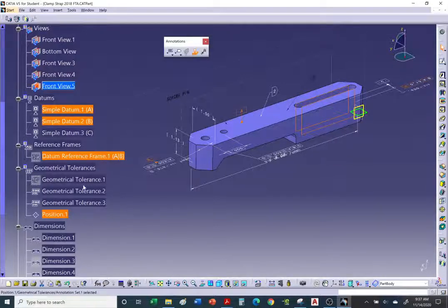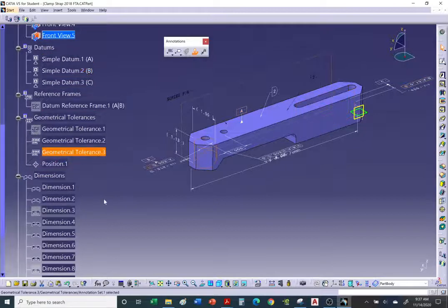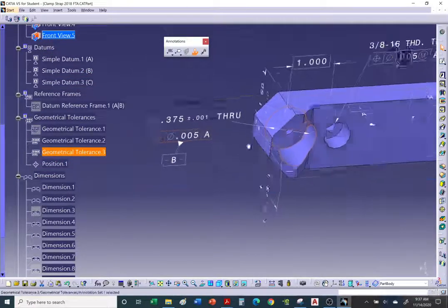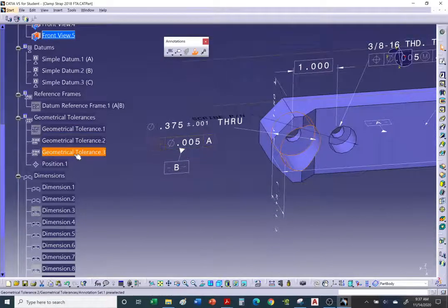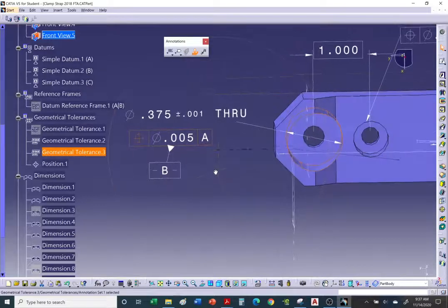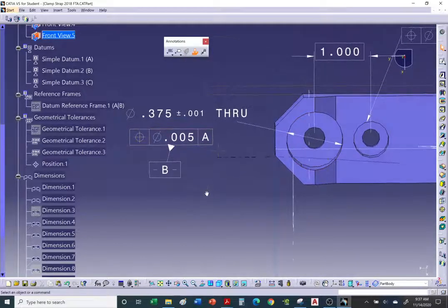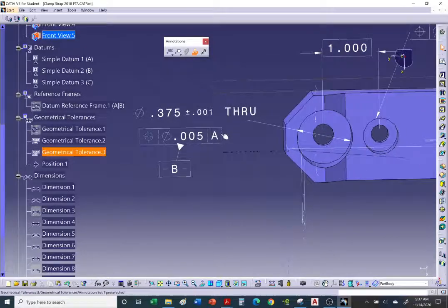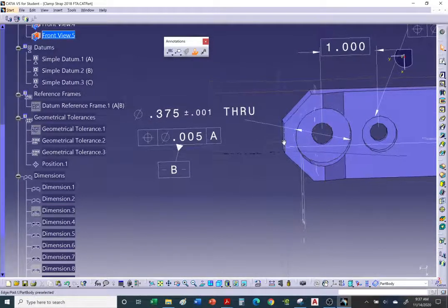All right, so once you add dimensions like diameter or length, you can attach frames for GD&T. Okay, for those of you that are not familiar with GD&T, geometric dimensioning and tolerancing, this is my tolerance for the location of this counterbore hole. So we have this hole and this larger hole, referred to as a counterbore hole.